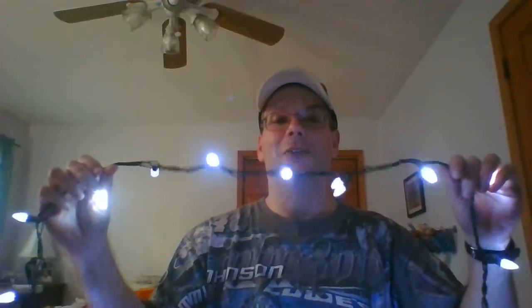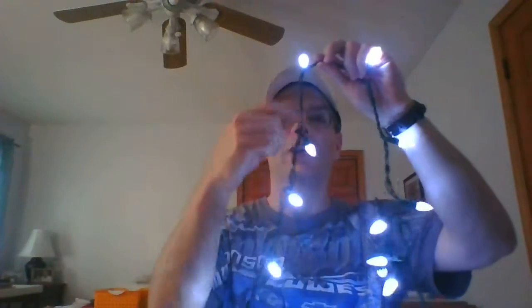Hi all. So you've all heard the old joke about the Christmas lights, right? The Christmas lights where one light goes out and the whole string goes out. That actually is a really good example of a series circuit, right? In a series circuit, there is only one path for current to flow. So if one element opens up, there's no way the current can flow in the circuit anymore, and current stops flowing. Because there's only one path for current to flow, the current is the same throughout the entire circuit.